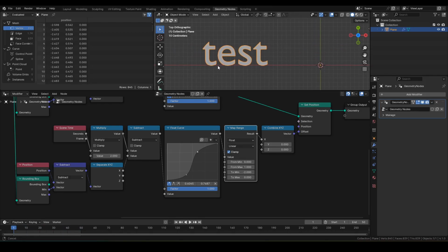The reason this is happening is because we're centering the initial position to here, and it's referencing the text like this. In this direction, what we want to do is make a center point right here and reference the text from right to left.